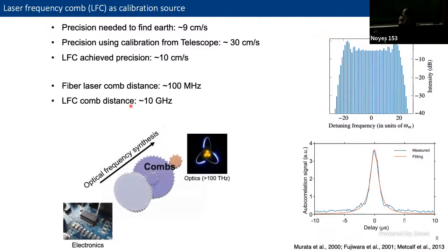Okay, so as a conclusion of this slide, if you think back on the animation we started with, we claim that the optical frequency comb is a link or bridge between the optical frequency and the electronic frequency. And what we're doing now is that we are taking the radio frequency source, which has very low phase noise, very reliable. We're taking that source as a driving source that can phase modulate a single frequency laser so that you can generate an optical frequency comb, or we call it electro-optic frequency comb. Using this process, we are up converting our stability and reliability from the radio frequency domain to the optical frequency domain. This process we call optical frequency synthesizing.